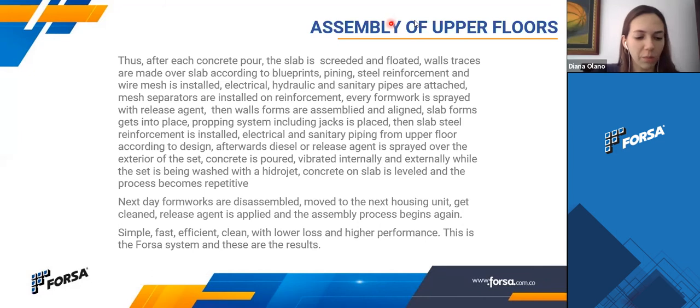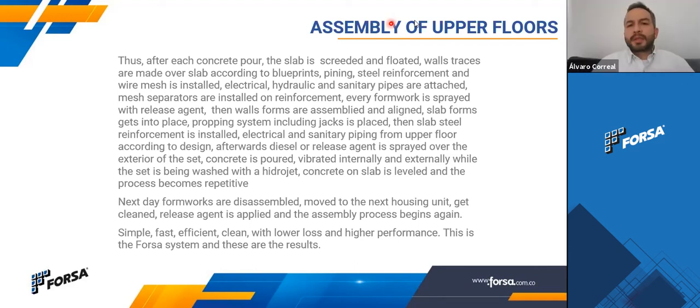There's another question, Alvaro. Someone is asking, how often does Forza recommend doing the maintenance on the formwork? Okay, Diana. You know that there are different kinds of maintenance of the formwork. There is the maintenance that we do daily, which is basically to have the scraper tool and the wire wool to clean every day, and to apply the release agent. This is the basic maintenance that you must do.